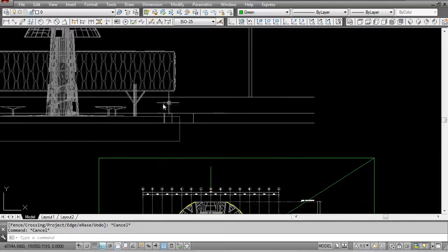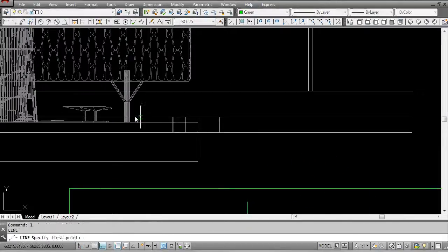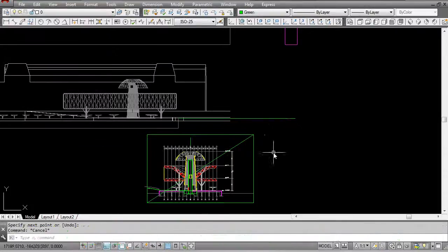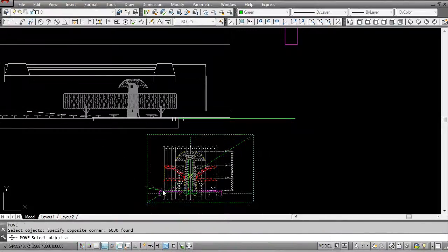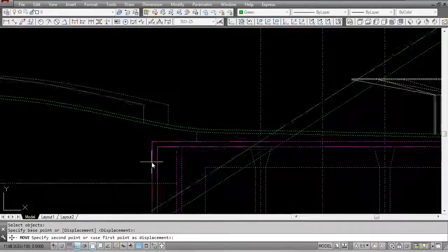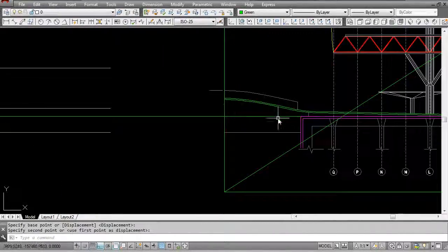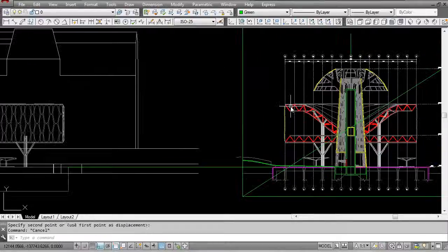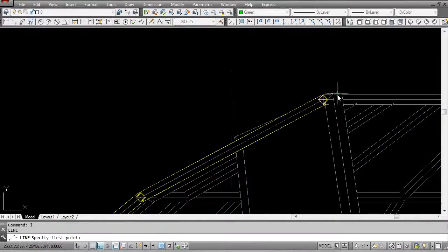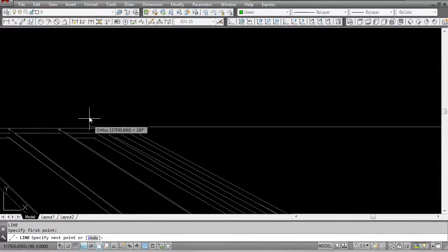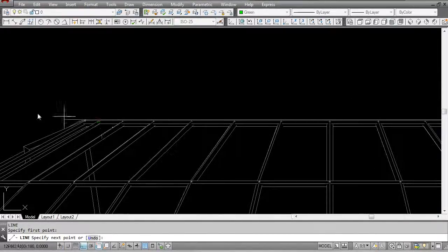Now I'm going to draw a temporary line out from the top of this plinth, and I'm going to move this temporary section of mine using the top of that plinth as a snapping point and apply it to that. Now the two drawings are exactly in line, and you can do a couple of tests. You can take the top of your tower, draw a temporary line and have a look that it does all line up. It should more or less be correct.